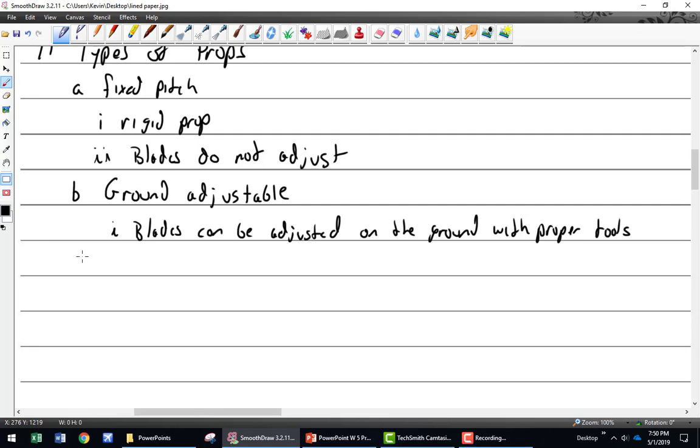The reason why is because when the air is less dense, the engine performs less, and so it still matches. So you're either going to go with a cruise type prop, a climb type prop, or an in-the-middle type prop. If you look at most aircraft on the type certificate data sheet, they pretty much give you just that range. There are different manufacturers, but if you really digest it, you're either getting a cruise, a climb, or in the middle. And guess what almost all airplanes came with? In the middle. And the difference between the two is not a lot, especially on a little 150.